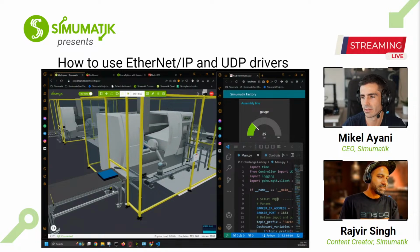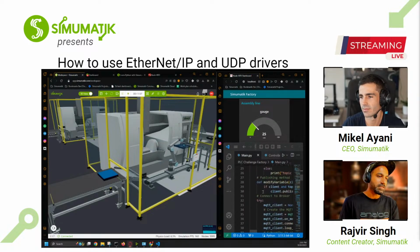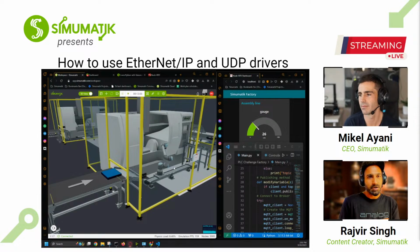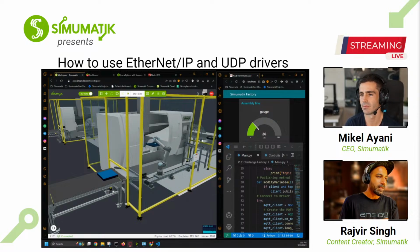And if you see on the right side, this is my Python code for that. Within this Python code, we have implemented MQTT. So we have a broker running on our computer. This broker can usually be anywhere; in this case, it's running on my computer. The Python is sending the topics to the broker, and then I subscribe to this broker with Node-RED. The gauge you see here, which shows 26 units, is the number of workpieces finished by the robot. Now when it places this workpiece on this conveyor, this will increment to 27.